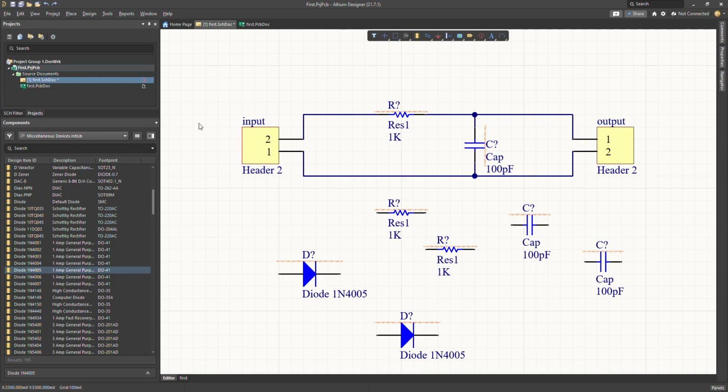What I want to mainly talk about is the order of processing the annotation. As you can see right now, it goes across, then down. You can change this to across, then up, down, then across, or up, then across. So you can just change these. If I change that to up, then down, and then press